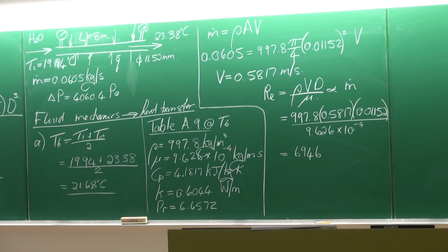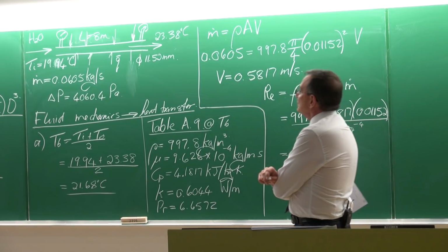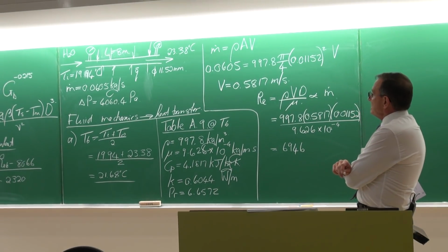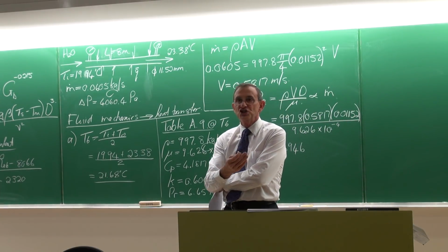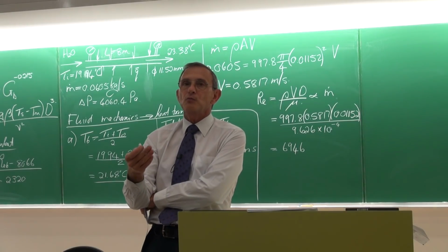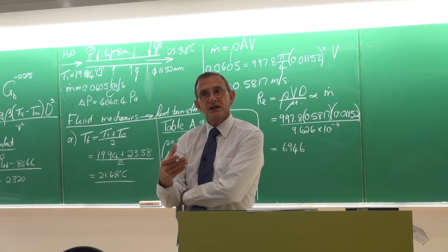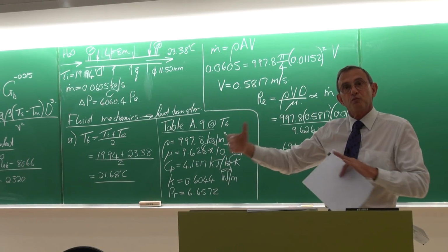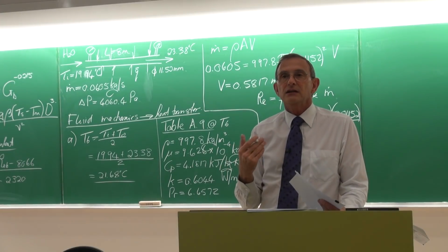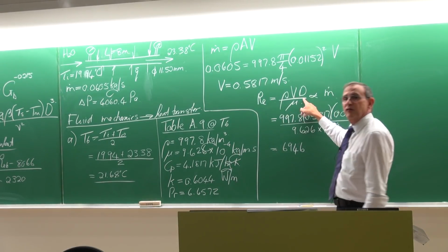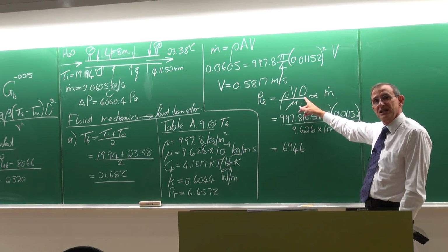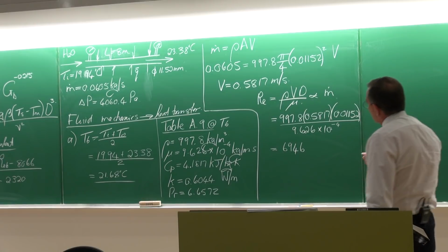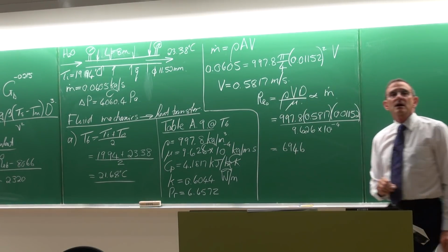Why is the diameter used in the Reynolds number, not the length? It's an important question. It is a decision that was taken by the people who originally did the experiments. If you look at the Moody chart, the Reynolds number is based on the diameter. The length, of course, is going to determine the total pressure drop, but the data has been presented in a form influenced by one or other variable, because it can be d or it can be the length L. Later on, when we get to a plate, you'll see it is the length L. So if we want to be more correct, we can say this is the Reynolds number based on the diameter d.